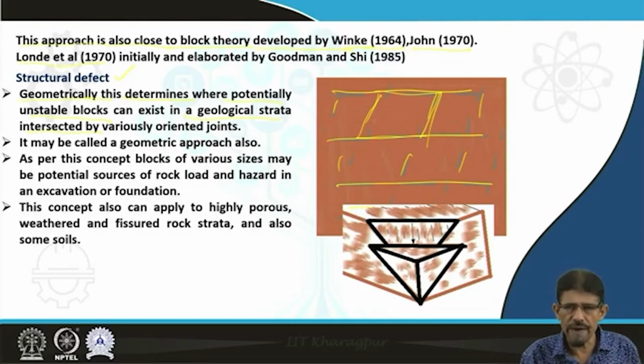Principally, the structural defect approach is due to the presence of joints or discontinuity. As per this concept, blocks of various sizes may be the potential source of rock load and hazards in an excavated opening or foundation, causing failure of the opening as well as slides near the foundation or displacement of the foundation. This concept may also apply to highly porous, weathered and fissured rock strata and some types of soils also.